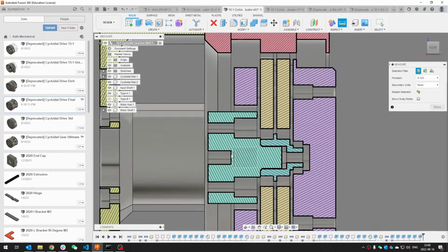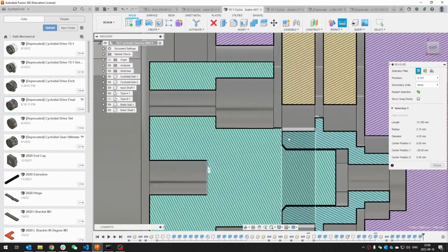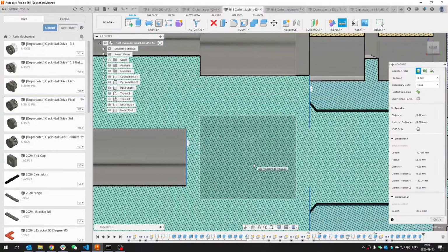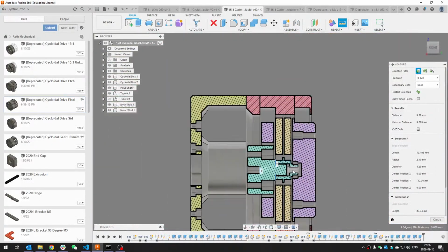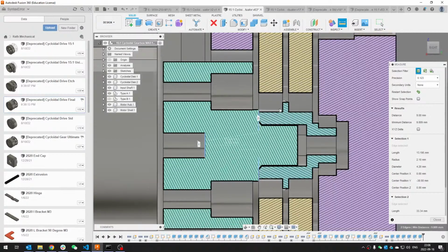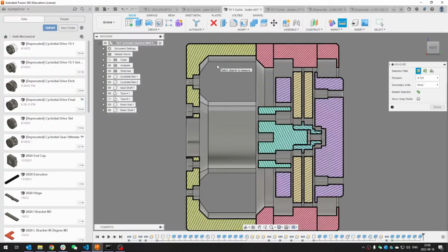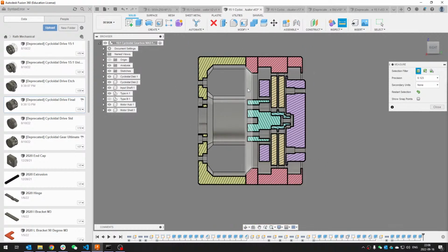How about this? This is 2. Oh my god. Okay. To this face, it's 9 millimeter. We can make it 2. So 9, that's a 7 change. Let's just make it 6 to be safe. We can just move this thing by itself to here, and then we have the space to account for the motor driver stuff. So we actually can have an integrated motor actuator.